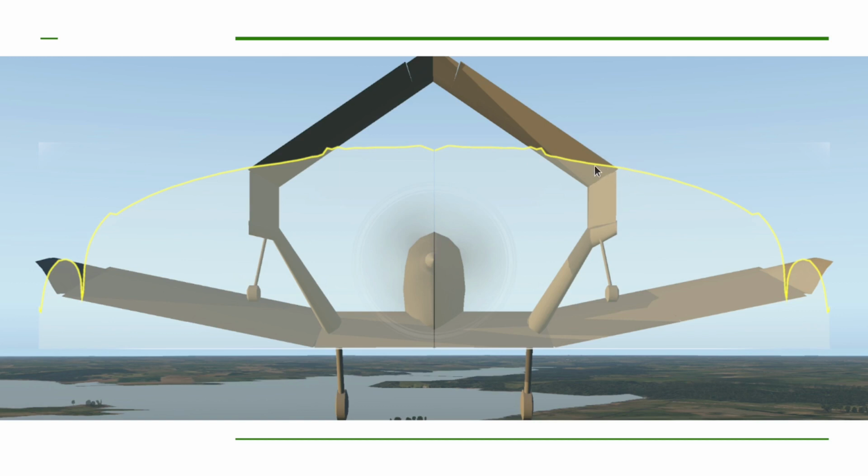We could just pick the middle value here, multiplied by that 2.5 feet, and the lift along that section would be 2.5 times 50, so it'd be 125 pounds along that 2.5 foot section. And of course here in the middle, this is almost perfectly flat. And that is what, 7 feet long? So if this was 50 pounds here, that 50 multiplied by 7 would be 350 pounds of lift from this center section here.